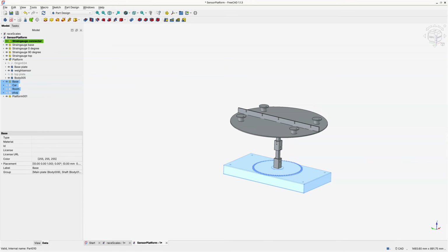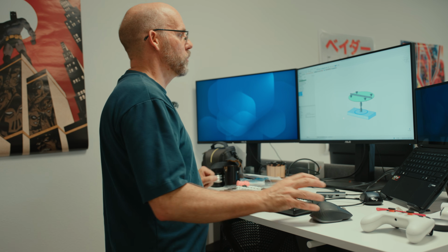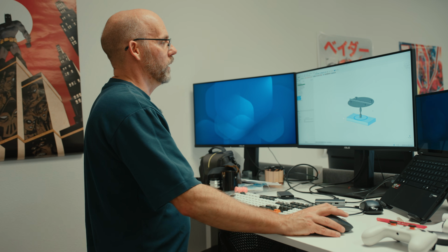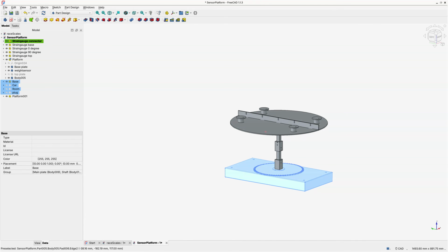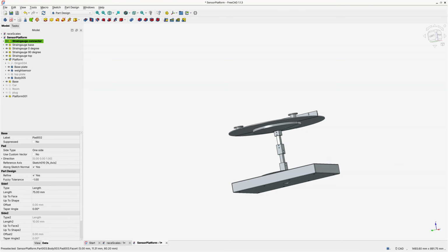So here are the 4 sensors that you can see that we just showed you that the car sits on. This is now scaled to a 1 in 10 car, so a very big one. The one we showed you downstairs is a 1 in 24, so the sensors will be closer together. There will be versions of this platform for every scale and every object we want to measure. There's 4 sensors there, and then that whole platform is floating on top of 2 of those strain gauges I just showed you, right here and right there. So this one and that one.